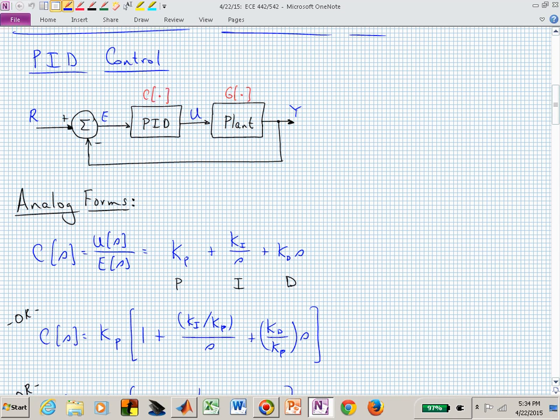Let's say we put in a 10, we want to go to 10, we might want to introduce an integrator if one doesn't already exist in our system in the forward block. And now we're assuming this negative unity output feedback configuration. The derivative piece does really just the other side of the coin. We need to worry about steady state accuracy, and we need to worry about transient performance.